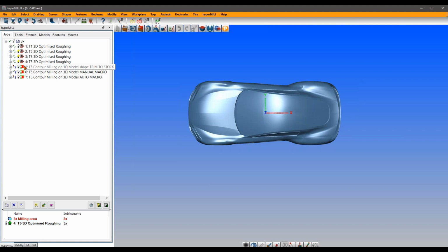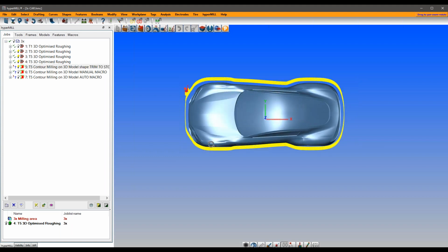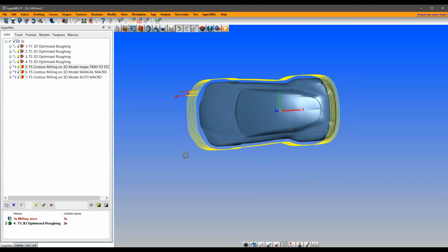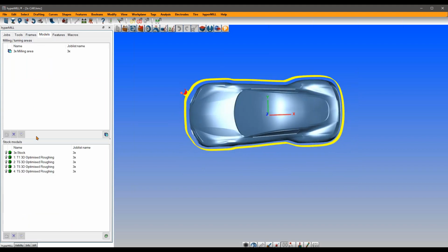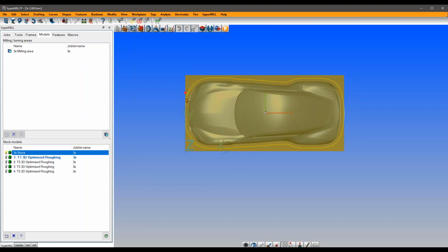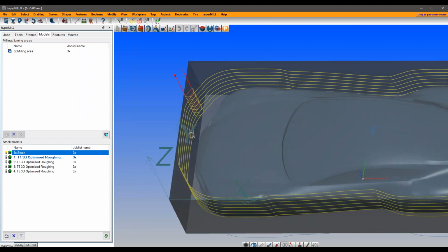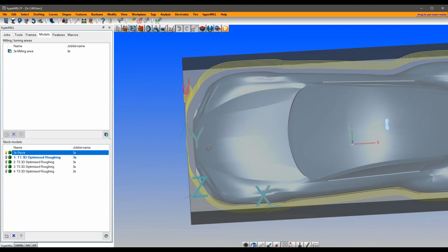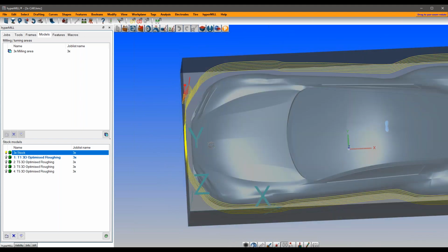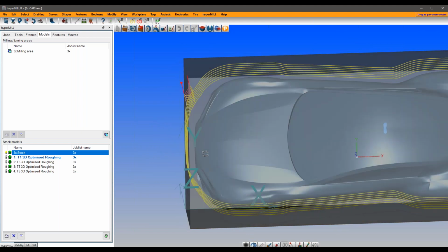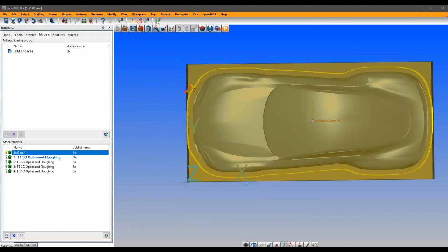So here I have a scenario where I've got a contour milling profiling around this shape. But let's consider that the stock scenario is the full stock block. And at this point, the engagement move and the cutting, not only is it plunging through stock, remembering that this is a 2D cycle, it's also going to be producing full slots.